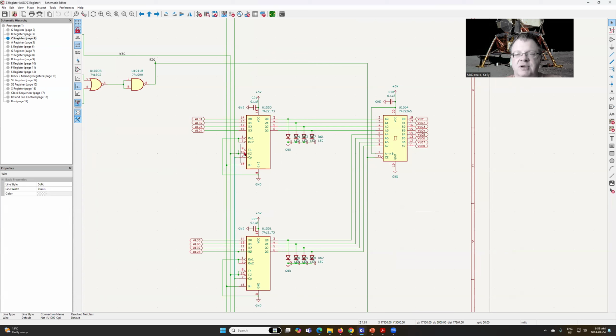And then we've got these enables, which allow us to write data in. This is where those control signals that we talked about come in: when do we write data into this particular register. On the transceiver side, again, we've got the chip enable that we're going to tie to the read signal.